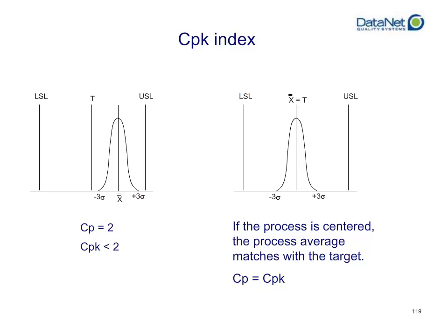Now, as for most industry standards, the tendency for most customers is that the benchmark is 1.33 CP, which is usually considered very capable. That's where you want to shoot for if you started off with either a marginally capable process or a completely incapable process.